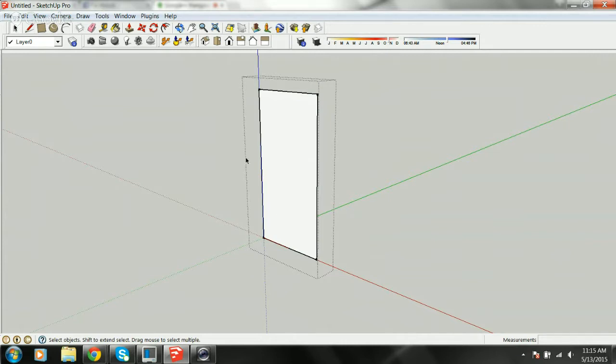Okay? So now I know the limitations of Shapeways in terms of the thinness of the material and how the details print. So there's no reason for me to create a 1 foot thick wall because that really doesn't translate to the thinnest material I can print in Shapeways and actually print successfully through their checks process. What I've kind of discovered is that between 1.5 inches and 3 inches is what you need to work with for a single plane. So for the sake of argument, we're just going to stick with 3 for today.